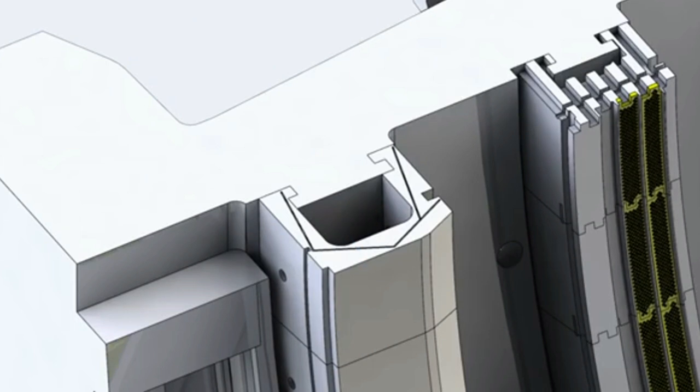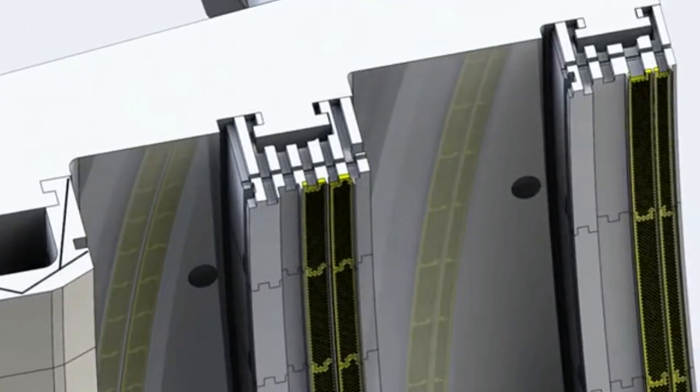The second and third stage shrouds have teeth that mate with teeth on the tip of the second and third stage buckets. This labyrinth seal minimizes tip leakage. For better tip clearance, a honeycomb seal is integrated on the second and third stage shrouds. This honeycomb is relatively soft material.